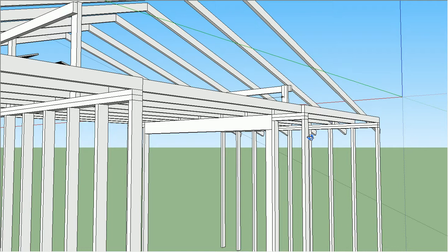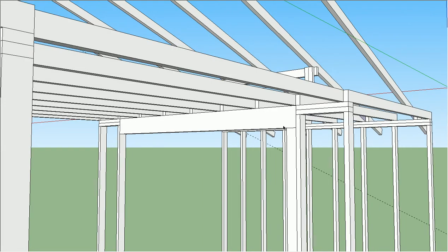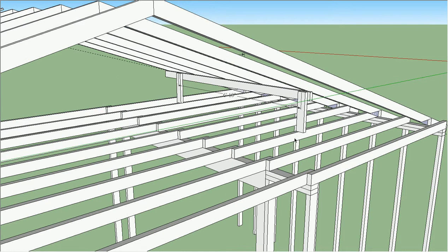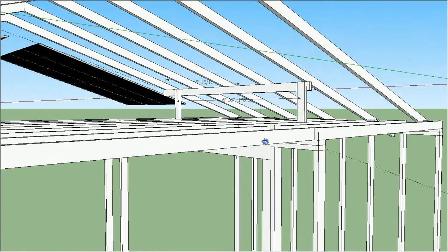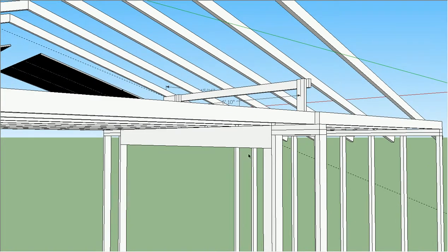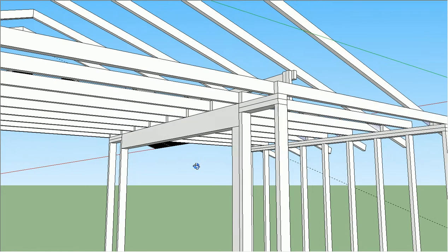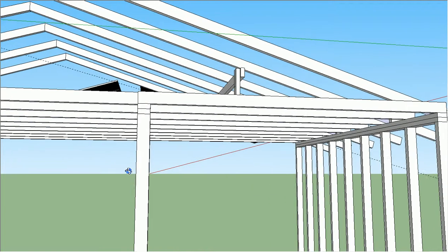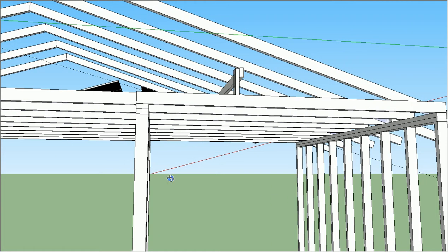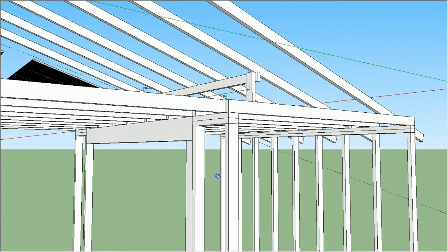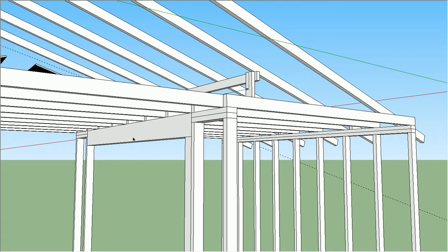This structure has a beam in it, but in this case, I don't believe the beam is affected. Well, actually it is. You see the load's going to come through this ceiling joist and make it to the beam just a little bit before that beam gets to the wall here. So the beam is also something you'd want to record in that case. The size, the spacing, and the span. Obviously beams don't usually have spacing, but they do have the distance from the exterior wall, which is the important thing for you to be recording for a beam.